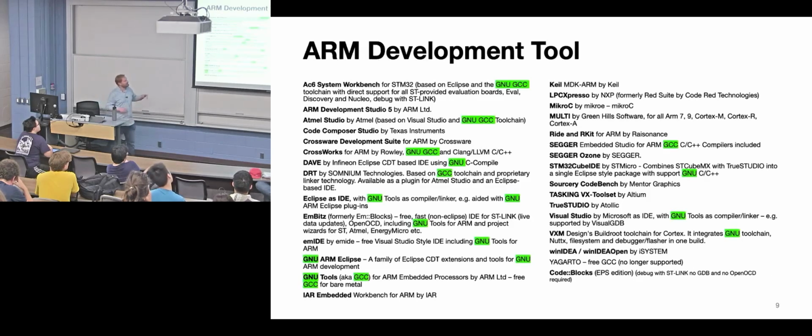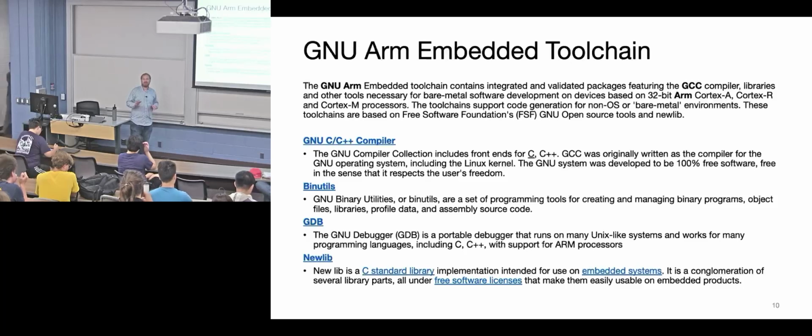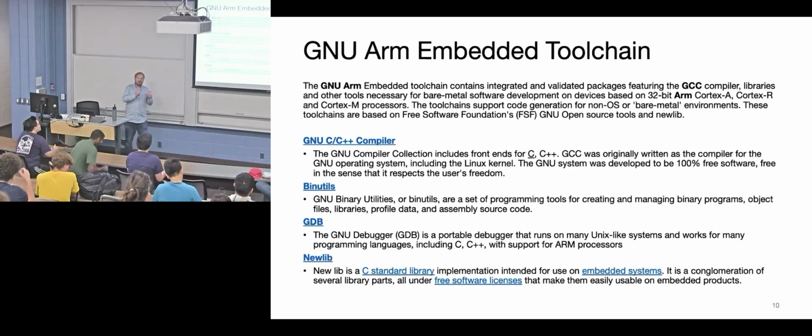The key thing is that underneath is something called GNU. GNU tools are embedded systems and computing tools that have been open sourced forever, and they're the backbone of all these IDEs. So if you want the lowest level possible control over your microcontroller, go look at the GNU tool chain. It is obscure, let's say, not well documented, but it gives you complete control. I had a project with energy harvesting nodes that would be powered off RF radio waves, and we had a whole class of bugs and issues that only exhibited themselves when you were running off of harvested power.